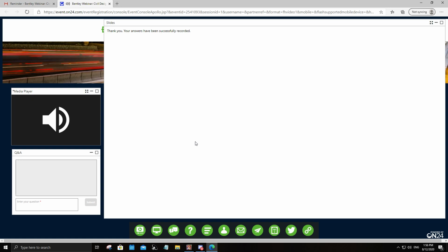I was a Civil 3D user as well before. In order for you to leverage getting your Civil 3D files into OpenRoads, there is a way for you to export them into LandXML. This is a standard civil interchange format for most civil design software.